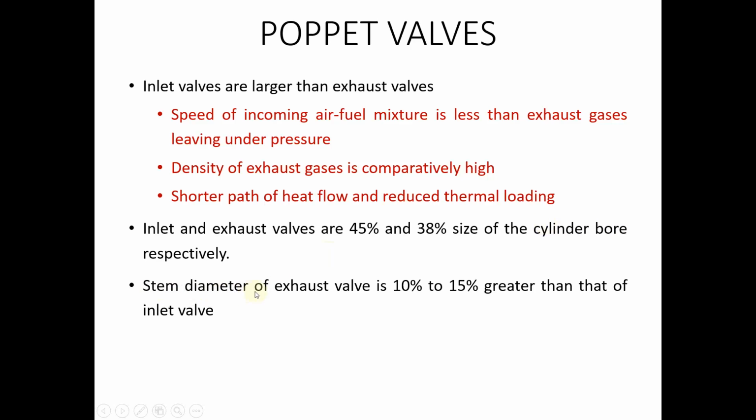And the stem diameter of the exhaust valve is 10 to 15% greater than that of the inlet valve. So here it is mentioned inlet valves are larger in the sense that the head portion is larger, and the stem diameter of the exhaust valve is greater, because as I mentioned, thermal loading occurs due to the high temperature in the exhaust valves, and due to this high temperature there is a chance that the valves will eventually fail due to the loading condition.